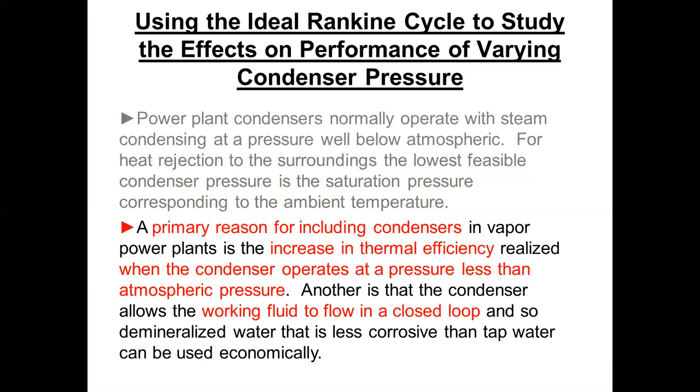And so it's less corrosive, and it's not only just corrosion. Corrosion is linked primarily to oxygen, but the minerals that are left behind will form a scale on the water side of the heat transfer components that basically is an insulating scale that reduces heat transfer and will really bite you on efficiency, because you have the same temperature differences between the steam side and the hot gas side, but you can't transfer the heat because you got a layer of scale on there, which has low thermal conductivity, low K, and hence acts as a layer of insulation.